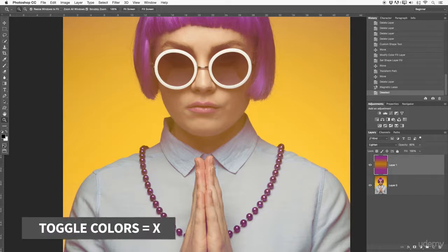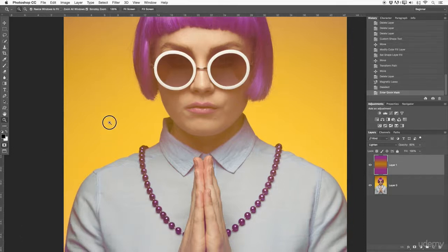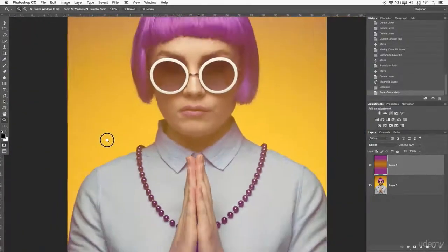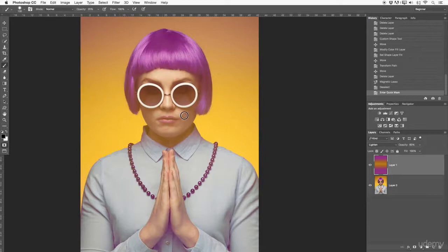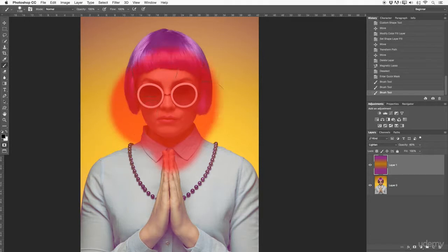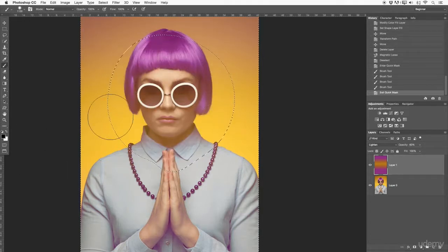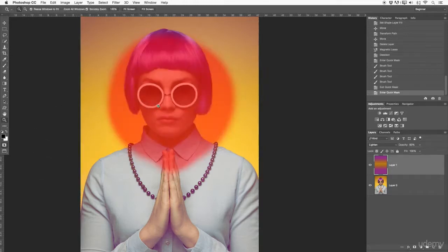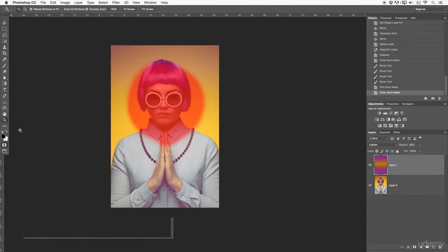Then also down here, we have our quick mask mode, again to brush. Sorry, let's get out of that again. Select the brush and we paint. And right away, we are masking areas. Also, let's work here just with 100% opacity. Okay, 100%. And then we are drawing a little bit. And out of this, right away, we have a round selection here. So we covered also the mask tool over here. Command D, get out of this selection again.